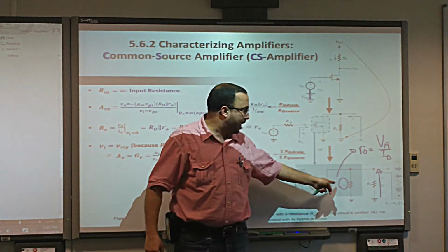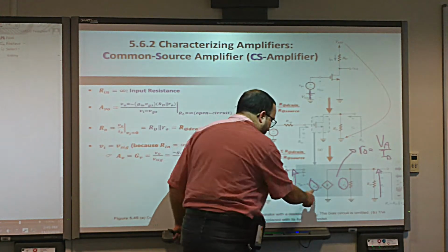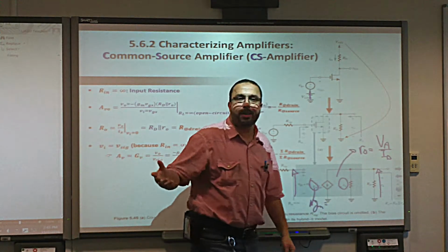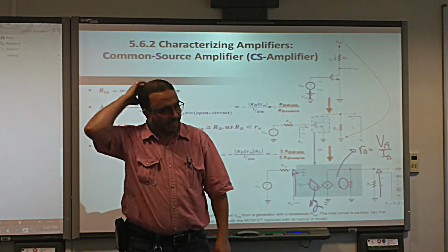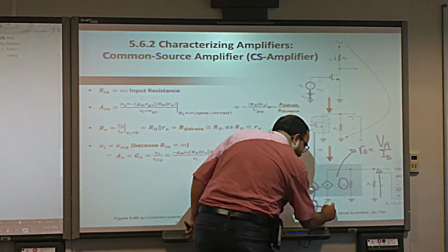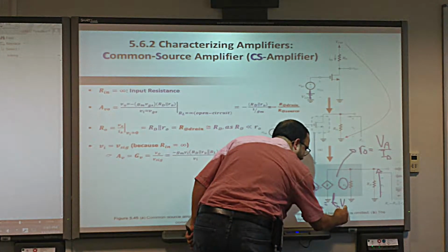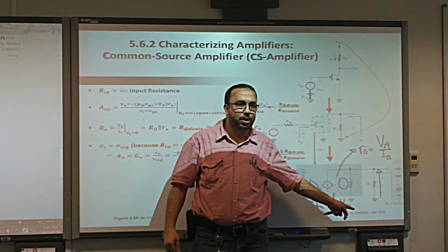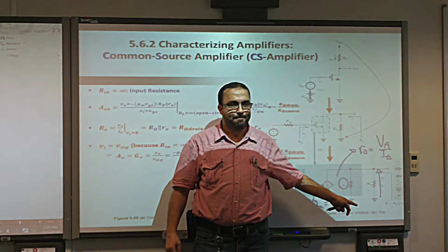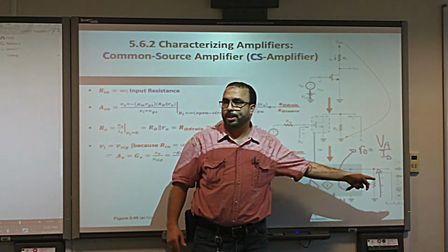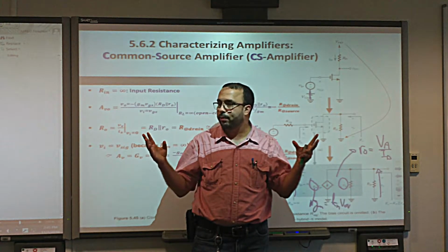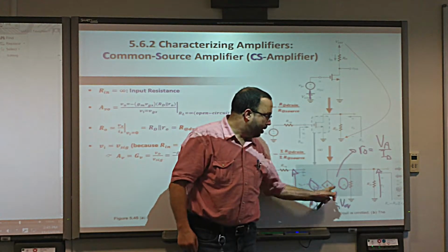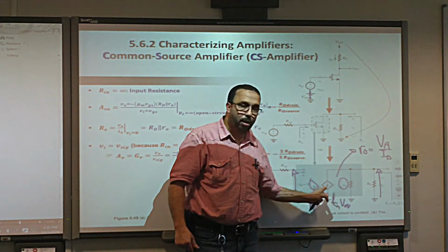And also in gm. What is gm? gm is equal to what? Kn V over drive. I heard somebody there, but she didn't raise her hand. That's fine. Kn V over drive. V over drive is also a DC value because it's equal to VGS minus VT. We're talking about DCs here. See? So we did not throw the DC voltages away. They are embedded in the parameters of the model.